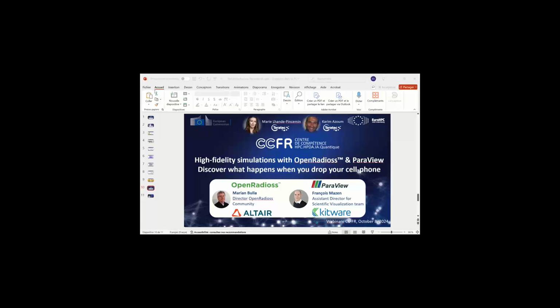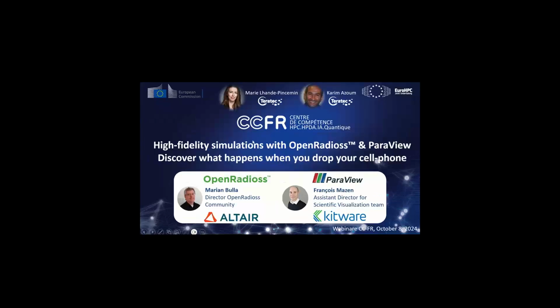Maybe a few words about movie making in ParaView. Movie making is basically creating a sequence of rendered images. As soon as you have prepared your scene, you just go to File, Export Animation, and then you export either directly to AVI or OGG, or generate a PNG for each time step, which I actually recommend, in order to make the actual video afterwards with dedicated software, if you want to add logos or things like that.